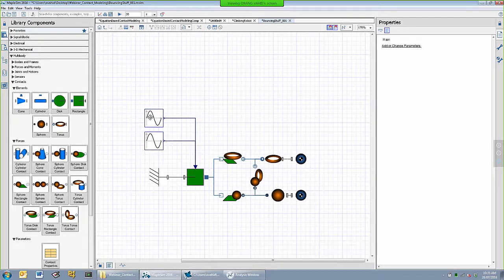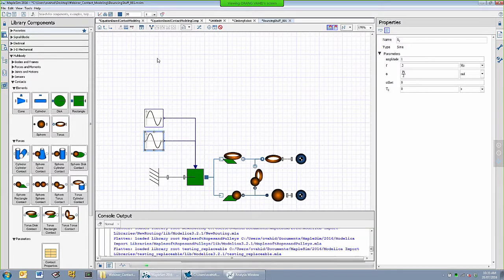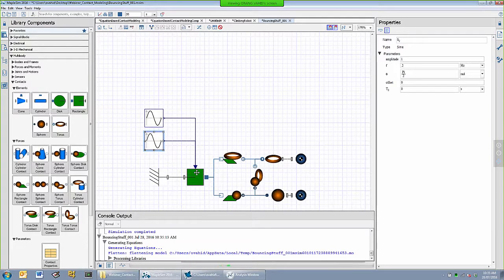So let's just have it go through sinusoidal motion along two perpendicular axes with a 90-degree phase shift, which basically creates a circular motion of the surface. The actual rectangle does not move, but its surface will have a virtual speed. Since all of these work with calculating relative contact sliding velocities, everything that comes into contact with this rectangle will feel that speed and act or react to it accordingly.